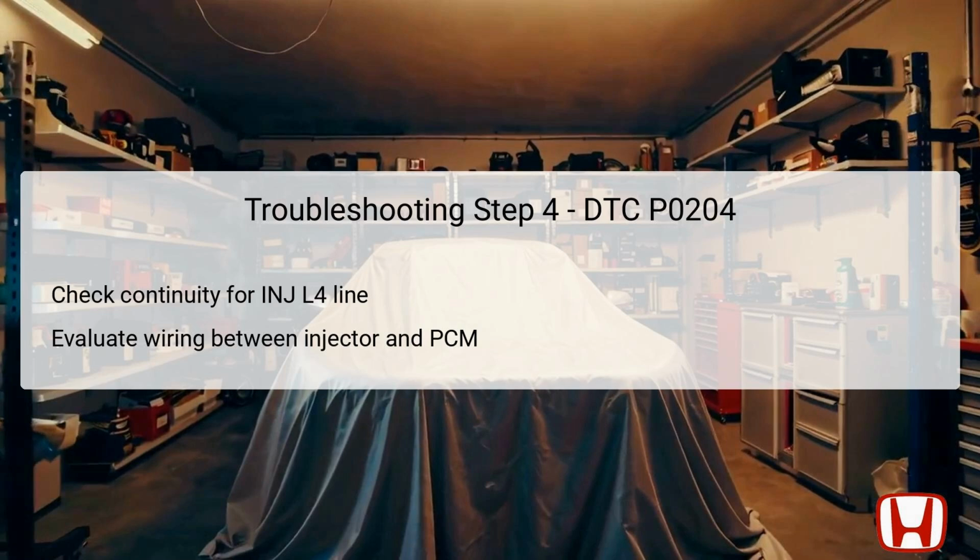On the other hand, if there's no continuity, it indicates an open circuit in the INJ L4 wire, which will need to be repaired before further troubleshooting can continue.